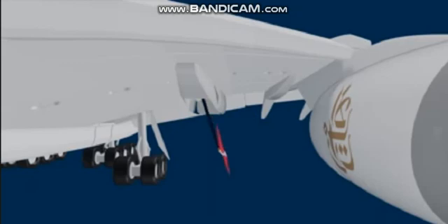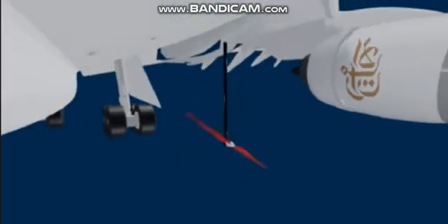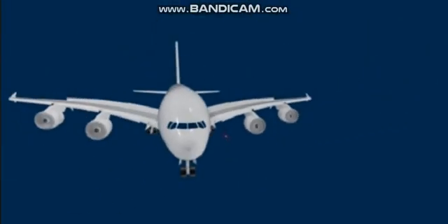This is the Ram Air Turbine. It is a small wind turbine that is connected to a hydraulic pump or electrical generator. The Ram Air Turbine is used only in an emergency, in case of the loss of both primary and auxiliary power sources. The Ram Air Turbine will act as an electrical generator. It will power vital systems, such as flight controls, linked hydraulics, and also flight critical instrumentation. Commercial aircraft can produce 5 to 70 kilowatts of electricity, depending on the generator.